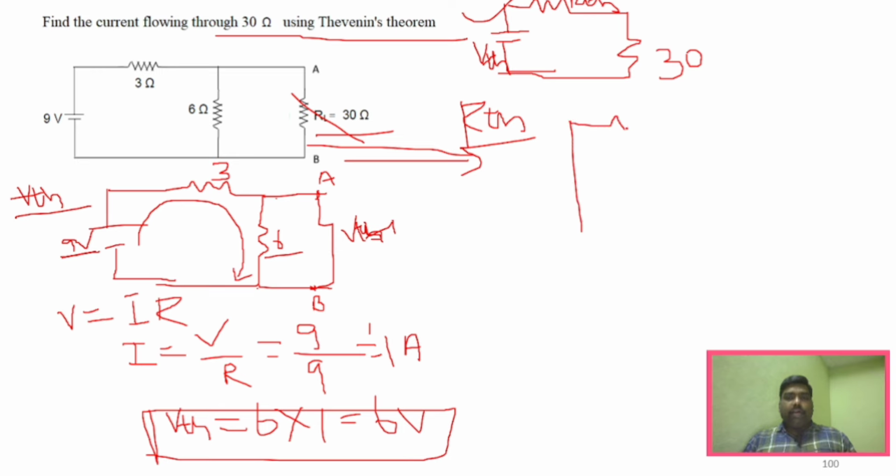And then we have this resistance, as well as this resistance. And we have to also remove the load, right? RL has to be removed, no RL, right? So now you see here there is no voltage source, nothing. So this is the circuit. So we have to approach this for RTH.